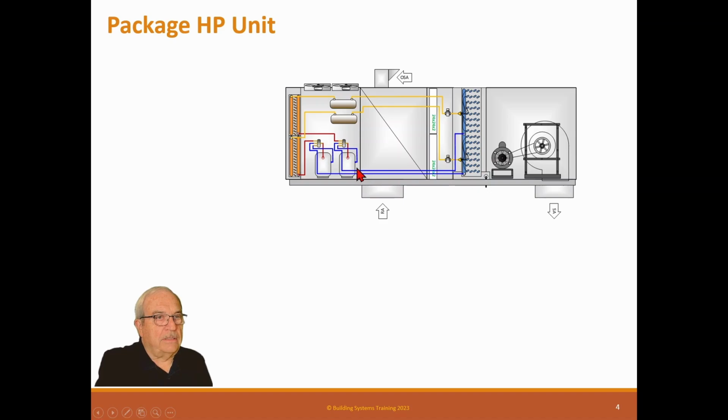Refrigerant circuit again takes the suction vapor and puts it in the compressor, pumps it up, makes hot gas. The hot gas goes to the condenser, through the receiver, and to the expansion device, cools in the evaporator coil and back. If it's in the heating mode, in the heat pump mode, the compressor takes the suction vapor. Instead, the four-way valve makes the suction coming from the coil, the condenser coil, and it takes it and pumps it up to the evaporator coil, which is now a condensing coil, and it basically is hot gas.